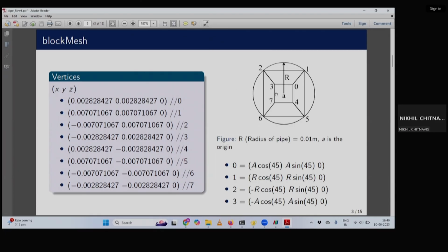For that, you have to define a bounding box, and based on that you have to create a mesh. So arbitrarily we have to create points and a surface. That means we have to create a control volume. For that, I think one tutorial is also there in the OpenFOAM tutorials, called 2D cylinder or something. For OpenFOAM, there are cylinder tutorials.